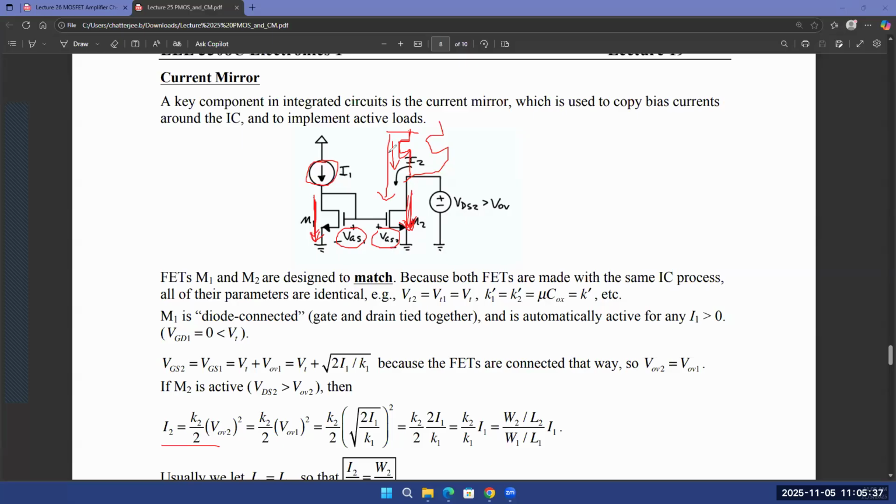Question? Does that mean that the MOSFET on top of it will force its currents to be equal? If you try to force 2 currents, yes, it can happen. But remember that currents will be forced only if you have a current source. So if you try to create another current source, you will force that current, yes.